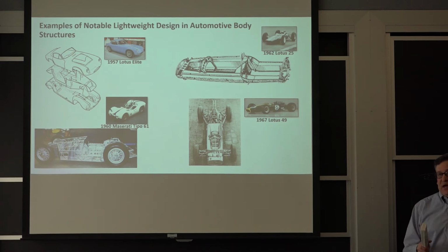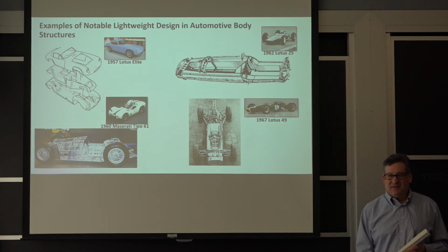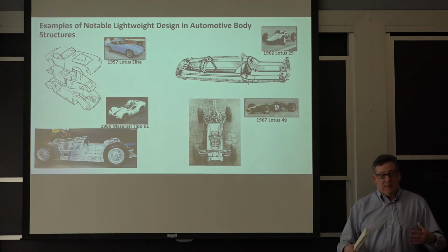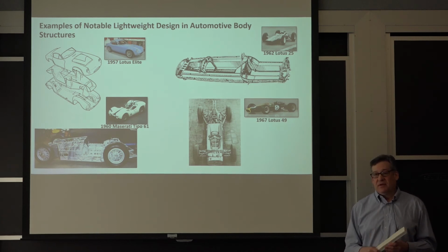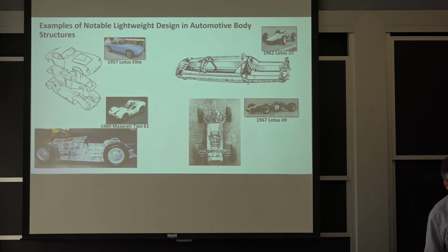But do you see a really neat opportunity with something Elon Musk has done recently? When you've got an electric motor, the vibrations are much lower, right? So all of a sudden, the possibility of using the housing on the motor becomes possible. You might be able to use that structure on the electric motor because it's not vibrating as a structural member. I guess the concern there is, okay, if it's a structural member and it strains, what's the gap between the rotor and the stator, and might they hit if it strains too much? I don't think anyone's tried it yet, but it's a thought.